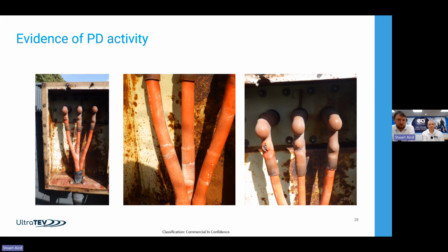Taking the lid off, following the measurement, you're able to see that there's been a lot of deterioration. It probably started around the cable crutch. That's then created an acidic atmosphere inside the cable box, and now the cable boots and everything are all deteriorating with a high amount of rust, etc. So definitely a good find, and something you would have wanted to act upon. All in all, a relatively easy fix at that point, re-terminating those cables.